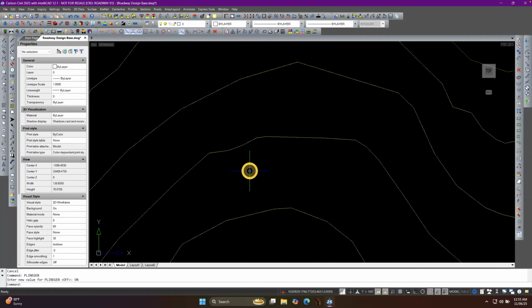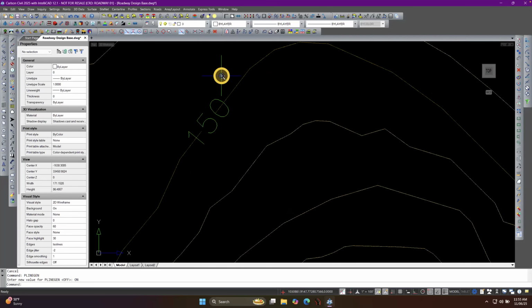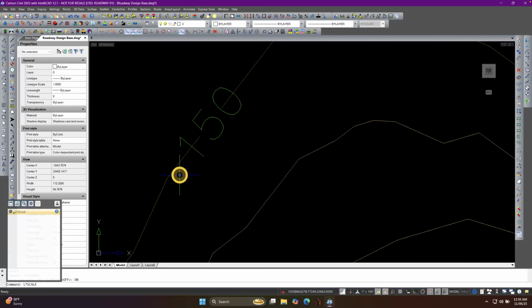That means now anytime I draw a pattern polyline, it will set that to yes. So it's going to do it. Now, I've also got that polyline set to 1, or the pattern set to 1. And you see, my dashes are still real tiny. And I typed my LT scale and it's also set to 1. So that should be okay.